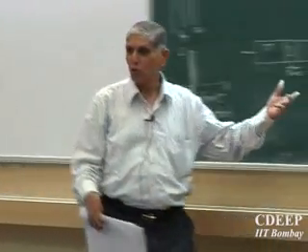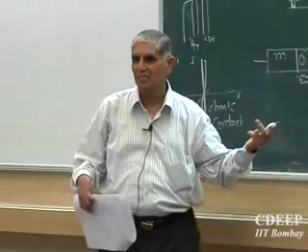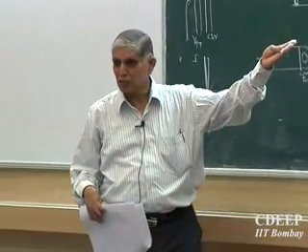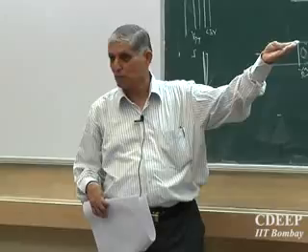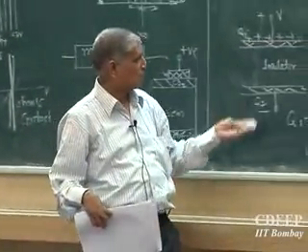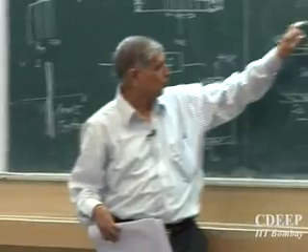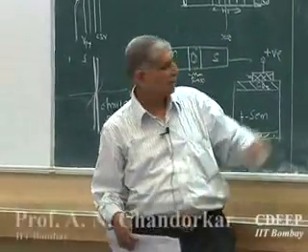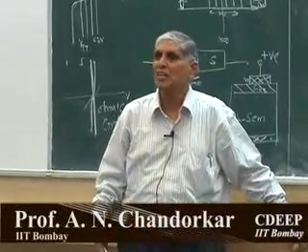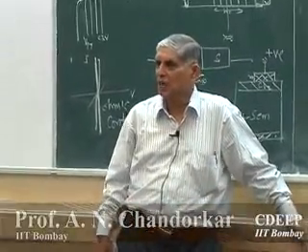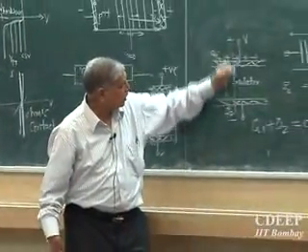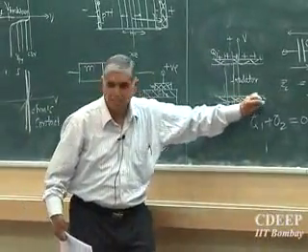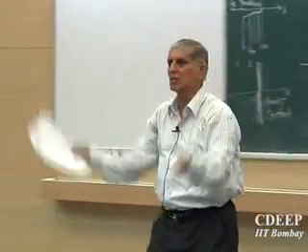On this basis, let's see how a MOS capacitor gives very typical characteristics, as shown there, compared with a normal capacitor. What is the direction of electric field if it is positive here and negative here? Field lines always start from the positive terminal and end on the negative terminal. Each positive charge must get an equivalent negative charge here, so that all field lines terminate from positive charge to negative charge. That's how the field method sees it.